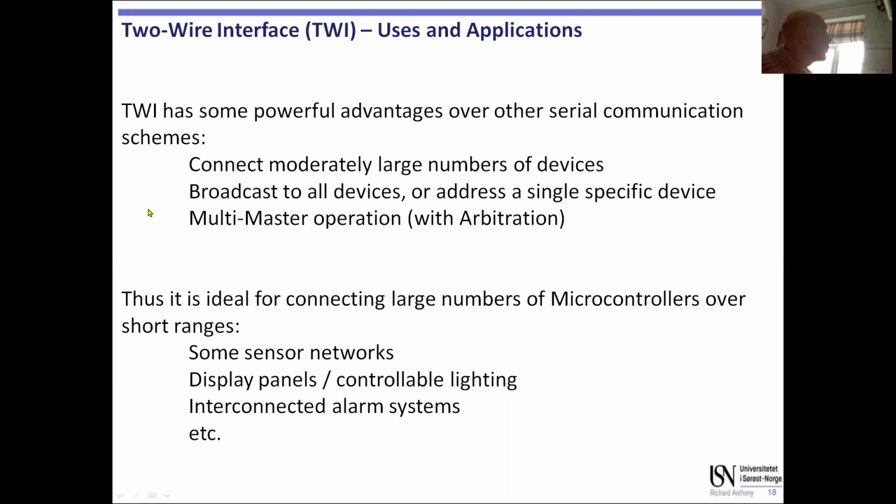This is also used in applications similar to SPI. I've used this to connect Atmel to Atmel, and I've connected 5 different Atmels together using this in one application. I've used it to connect RFID readers and LCDs, so the same kind of devices that you might use with SPI. And of the two schemes, SPI is simpler.